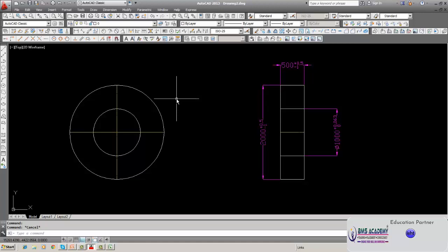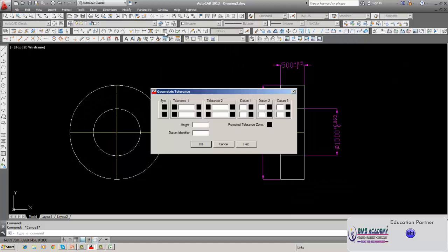But there is one important factor. With this axis, the bore and the OD should be coaxial or concentric. Within what value? You cannot be 100% concentric, but it has to be concentric within a certain limit, so you judge based on the purpose you need and your knowledge. Here, if I click, the symbol will be this concentric. This means both should be concentric. You click on this. Say you want it to be within 0.02, let us say.